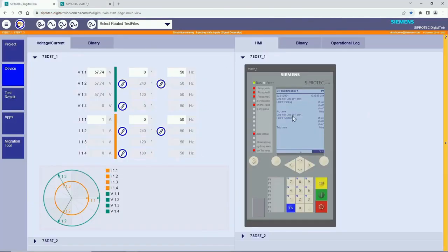So we see, okay, the device has tripped, we get all the messages, but all messages will also be flagged in this test mode with this little test flag, so that you can see in your substation automation system, okay, don't worry, this is only a test, not a real fault. And no binary outputs are getting on, only if you want them to get on. So this can be decided in the configuration. Do I want the binary outputs to get active or not?